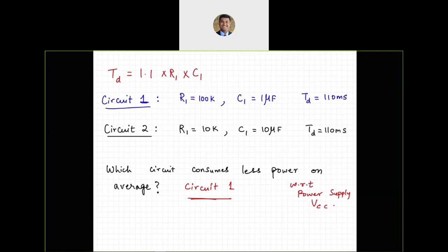It is very difficult to do that in Analog Discovery because I'm trying to look at how much current is coming out of the red power supply. So I would have to put a current sensing resistor in front of it, monitor the current that flows through the resistor, and then do that power calculation as an average.